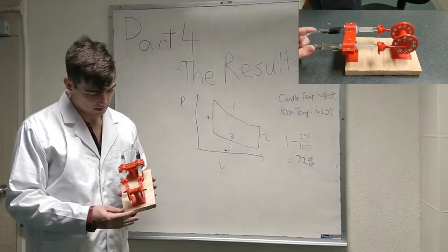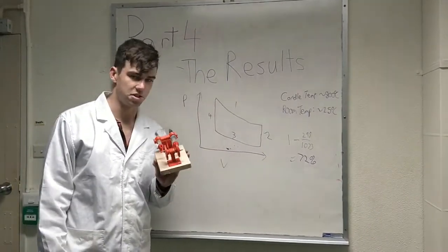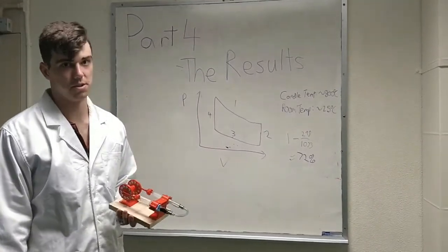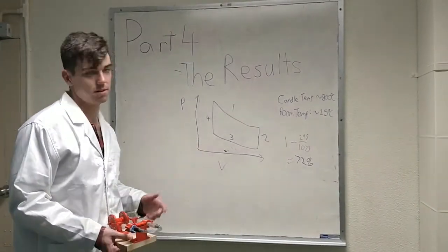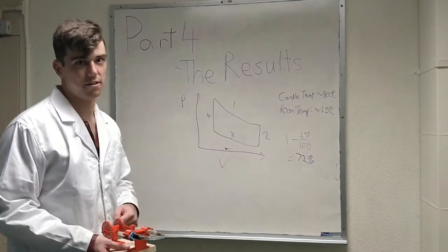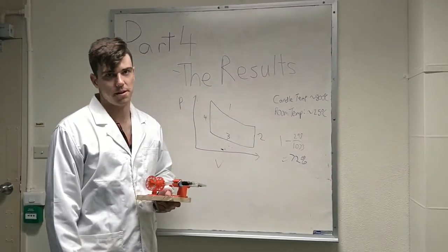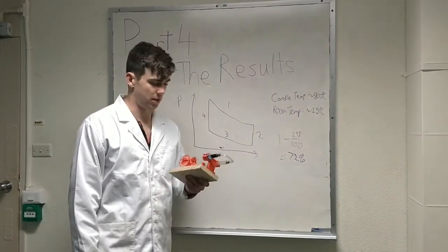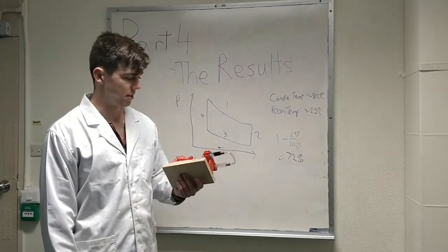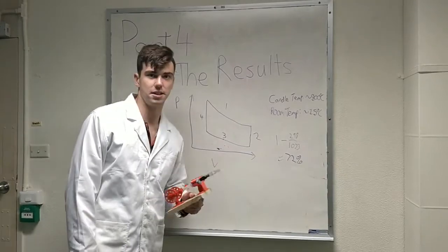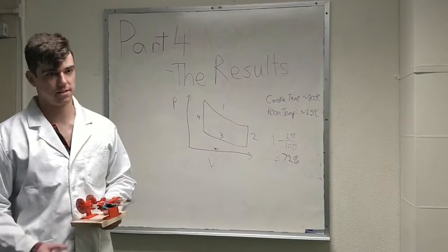Furthermore, the flywheel is slightly offset from the syringes, which would also likely increase friction and thus reduce the efficiency. Despite this, you can still draw parallels from the cycle, and this is solely based on the amount of kickback from the engine we did get. As the Stirling engine did not perpetuate its motion, we cannot get an accurate analysis for the amount of work done or the potential work done by this engine. As a result, it's increasingly difficult to calculate the true efficiency of the engine, as we weren't able to get power readings which were necessary for it.